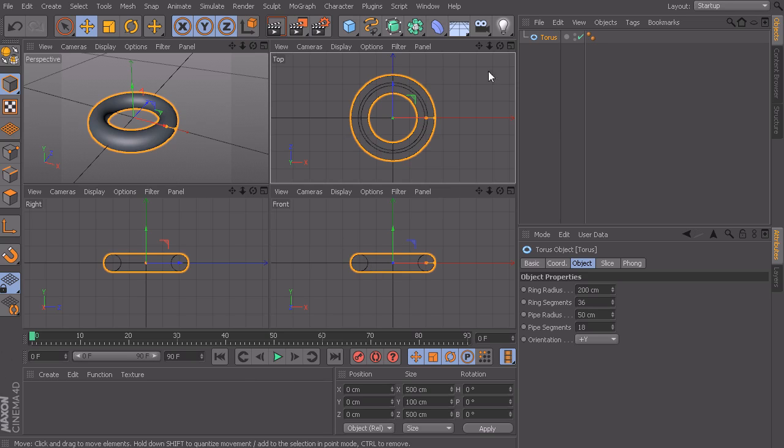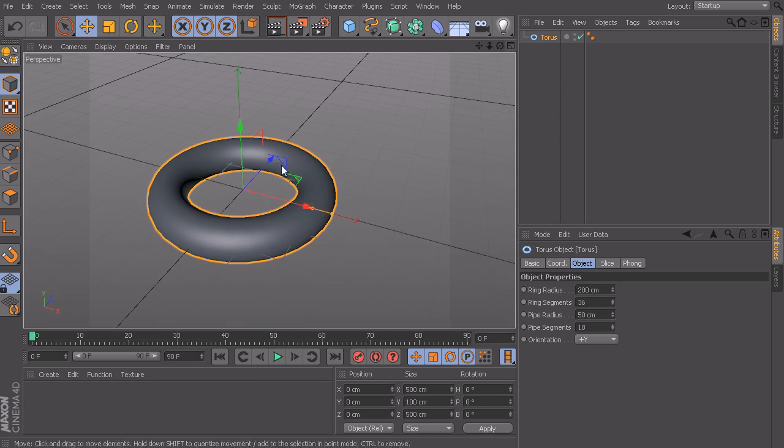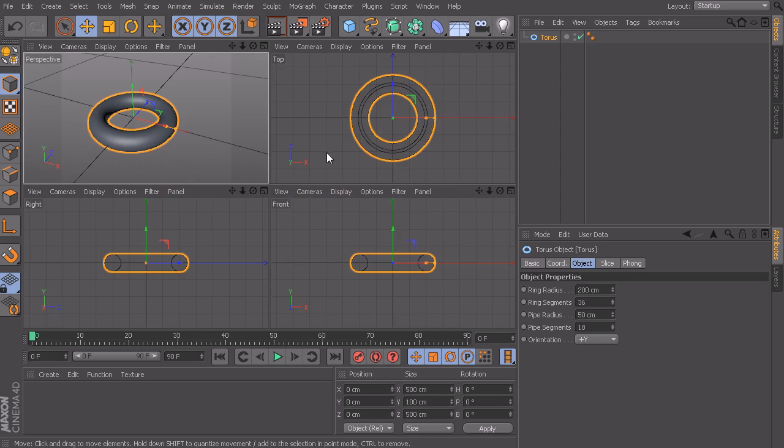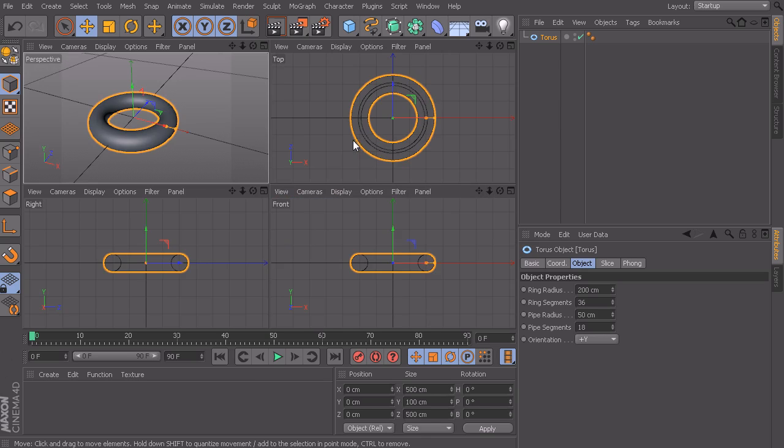Now in any of these viewports you can see we have the same little navigation icons up here. We can click on this button and maximize any of our viewports. We can also, as an alternative workflow, if you have a 3-button mouse, an easier way of getting through these is to just simply middle click anywhere in your viewport, and by just simply clicking with my middle mouse button, that'll bounce us to this 4-panel view.